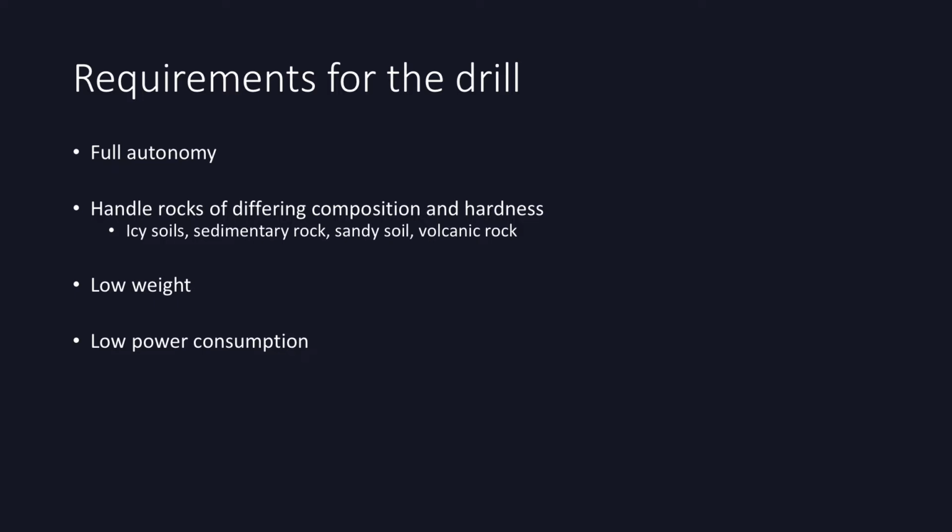To cope with bit jamming, the drill needs to be jettisonable, otherwise the whole rover is in danger of being stuck. Furthermore, a good balance needs to be found between compact design with short drill segments that can easily be stowed away and reduction of critical breaking points. The drill string is more vulnerable as it gets longer and consists of more separate segments.